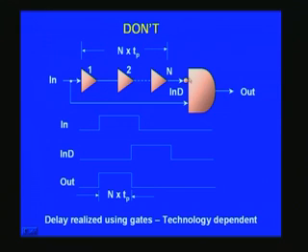So this is inverted here and fed to the gate, and the input is also fed to this gate, with a view to getting a positive pulse as the final output from the two inputs that we have here. This input is basically from, as I said, a push button switch. Of course, you may have to have proper debouncing, and that is implied here.